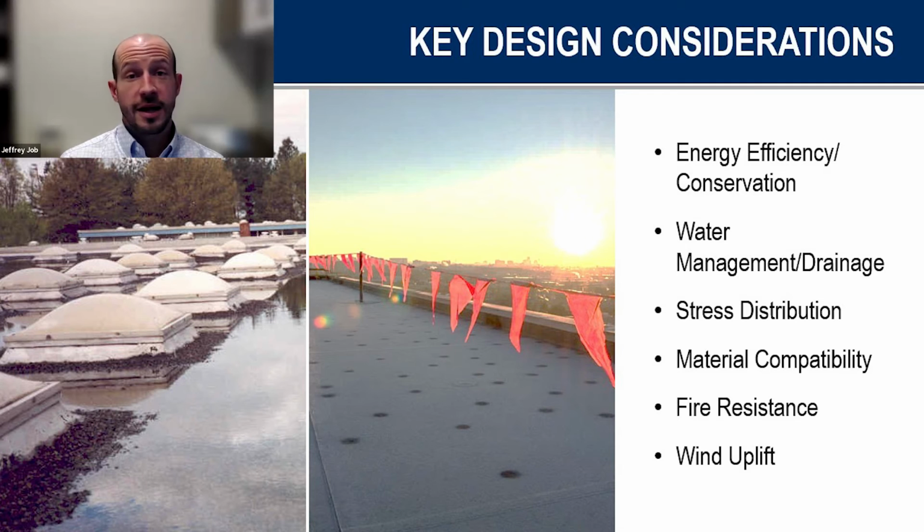Sure. Really, it's driven by energy code. A lot of that is based on ASHRAE 90.1, which tends to be the model standard that a lot of municipalities use as a reference, or the actual I-codes. IECC, for example, generally adopts or references a lot of the standards coming out of ASHRAE. Nonetheless, what requirements apply to your job site is going to be driven by what energy code, and what version of it, has been adopted in your market or in the area where the project is, and that's really driven by the climate.